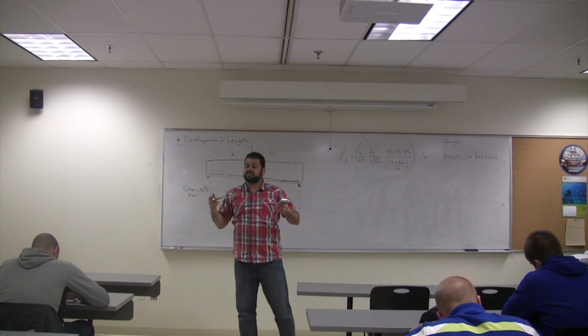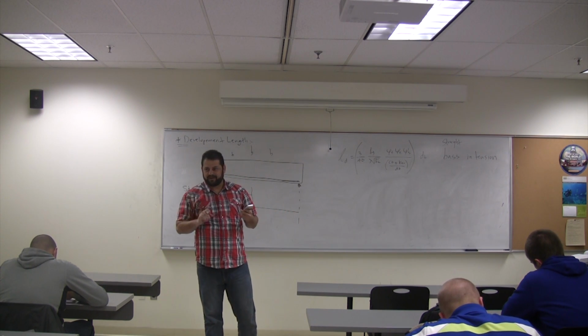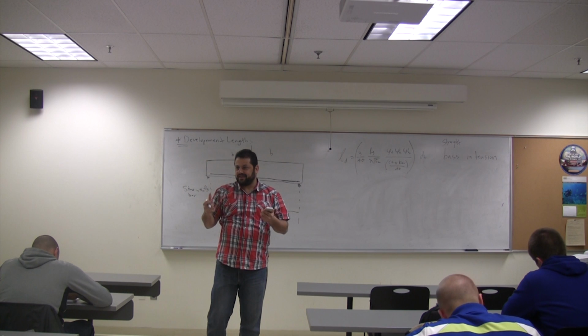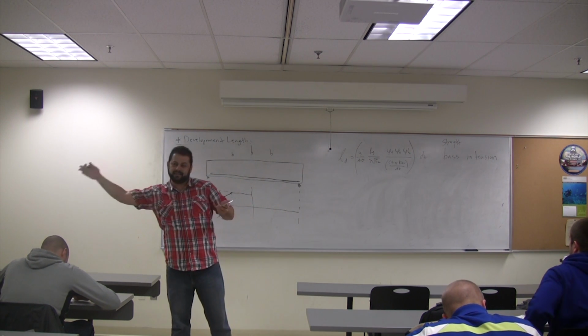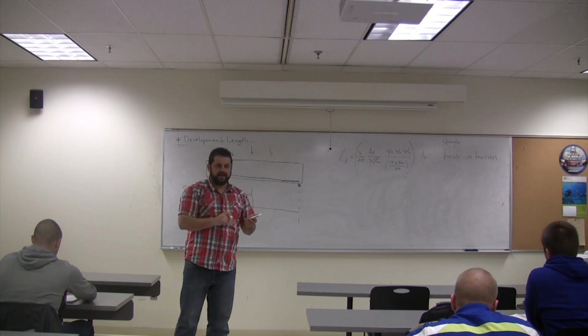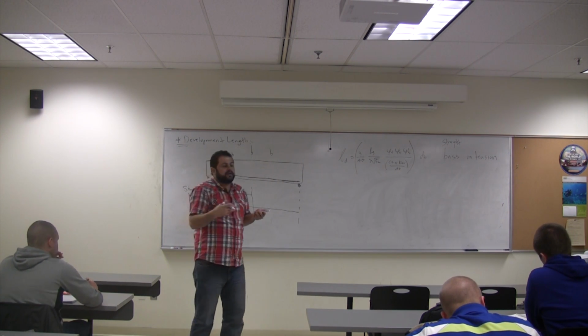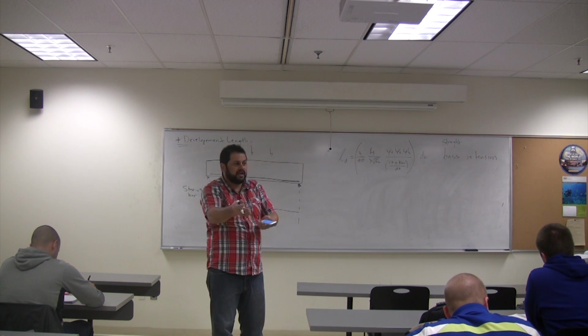If the bars are straight but in compression, the development length will be smaller. The required development length is smaller. Why? Because in tension there will be cracking, so you will require a higher embedment length to develop Fy. Now, what if we can't accommodate this requirement? You need 50 inch and we don't have this space.